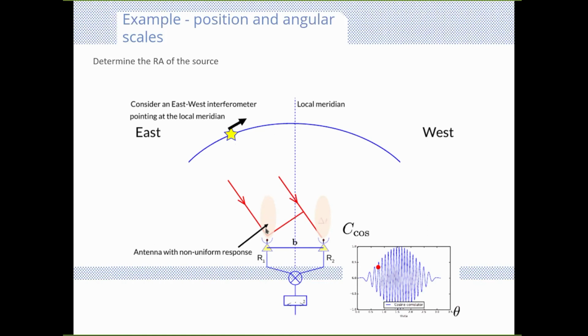The interferometer is modulated both by the antenna far field response and by the integration period, so there are two areas of modulation, where this fringe is reduced in amplitude by a sinc function and by the far field response.